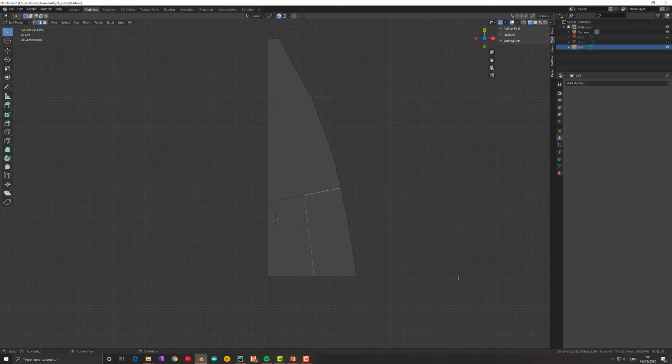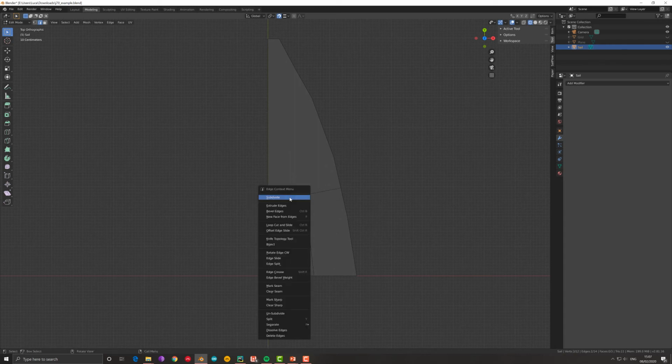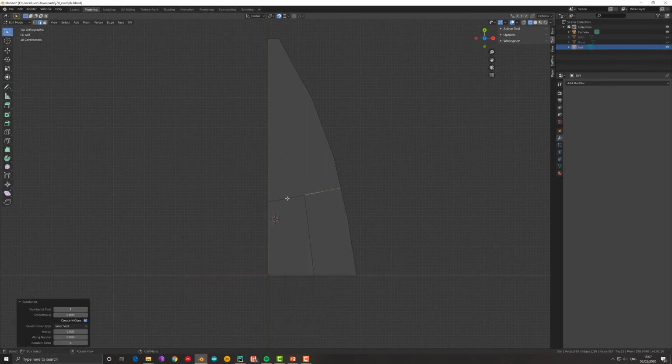If you look at the design on the right side, they irradiate from the lower corner, which is there, and go to this middle line. We can use a knife as I'm doing now, and I can cut a number of panels like that. But the best thing is to go and subdivide that edge in two, and subdivide also the other edge in two. Okay, and in this way I have already a vertex. So I select the other vertex, keeping shift pressed, and then J, and in this way I have created the cut in the panel. I do the same for all the other couples of vertices.